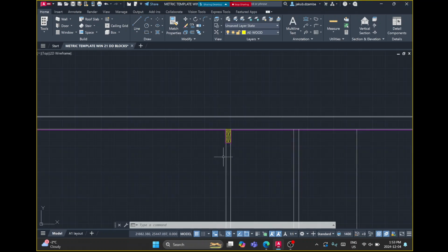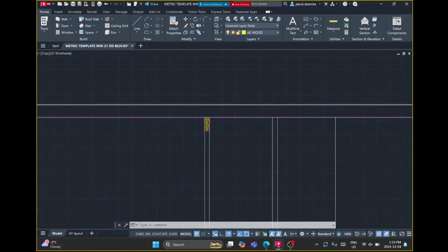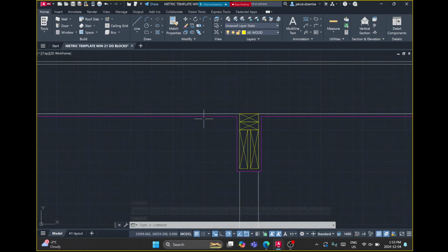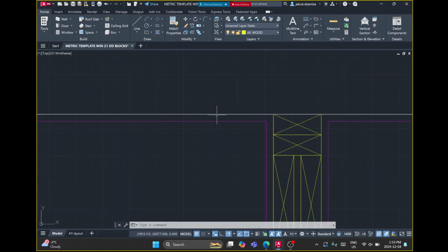How much did you offset? Sorry? The polyline? Oh, I just, whatever this distance, I'll check. I can't remember if we did 16 millimeters for drywall or 12 or 13. It's the difference between 5/8 and ½ inch. Different people prefer different things. I did 13 millimeters.